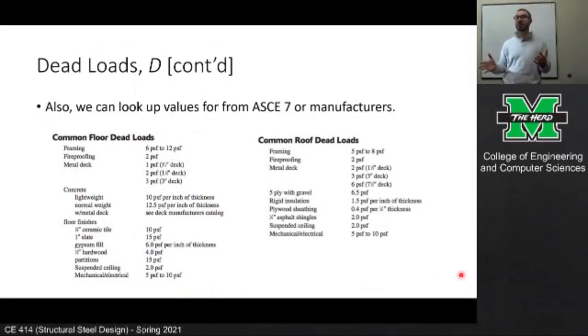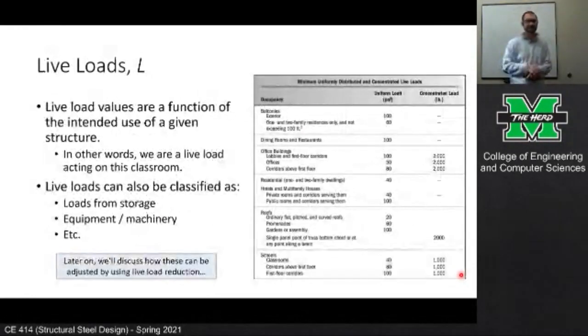For those of you that had me for structural analysis last semester, remember these loads, see how they're listed in PSF? Remember how we would take tributary area and then collapse that into a line load and then use that to distribute? So you can sort of see the connective tissue between this and structural analysis last semester.